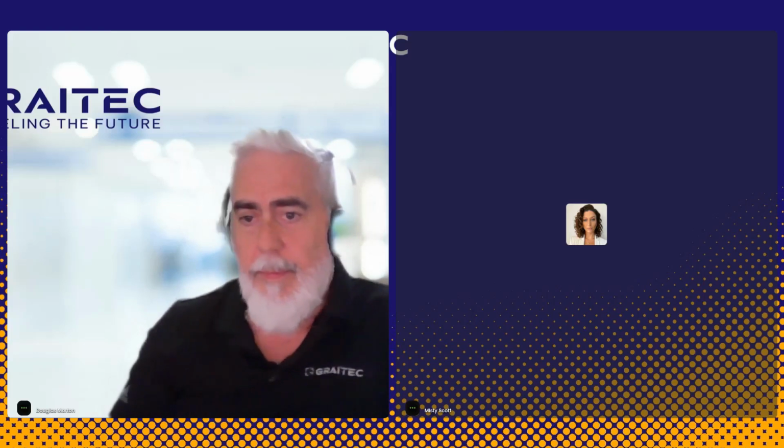Perfect. Steven asks, are the connections embedded into the current model, or can they be saved to be used in other projects/sessions? Yeah, so the custom connections, that folder that I just placed in the chat window, if you save them to that folder, they become available to every project that you're working on. So every time you open up the custom connection tool, regardless of what DWG you're in, it's going to be there, it's going to be available.